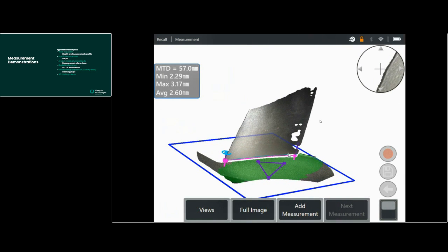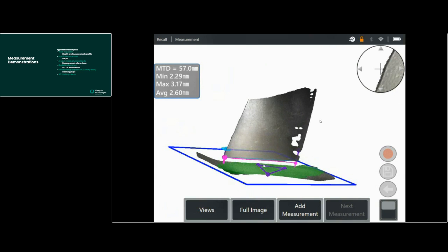So blade tip clearance, a very powerful measurement technique that saves an awful lot of time doing those measurements manually. If you are doing it all by eye, it's likely that you'll get different values associated with the minimum, max, and average that you get here. These correspond to many images, many measurements captured in this scene using the green long-range 3D phase measurement tip.